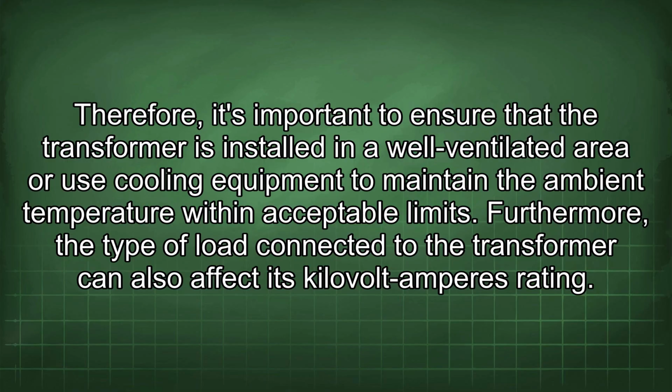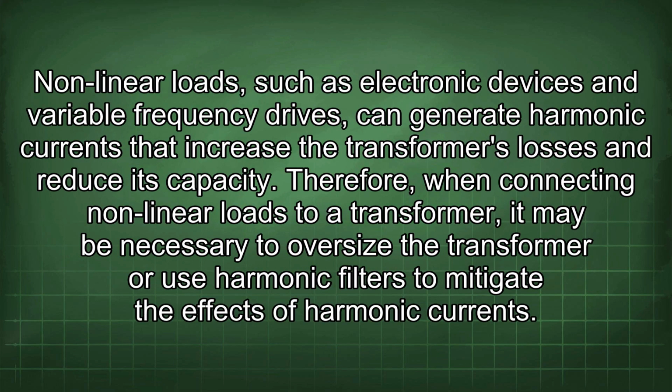Furthermore, the type of load connected to the transformer can also affect its kilovolt-amperes rating. Nonlinear loads, such as electronic devices and variable frequency drives, can generate harmonic currents that increase the transformer's losses and reduce its capacity. Therefore, when connecting nonlinear loads to a transformer, it may be necessary to oversize the transformer or use harmonic filters to mitigate the effects of harmonic currents.